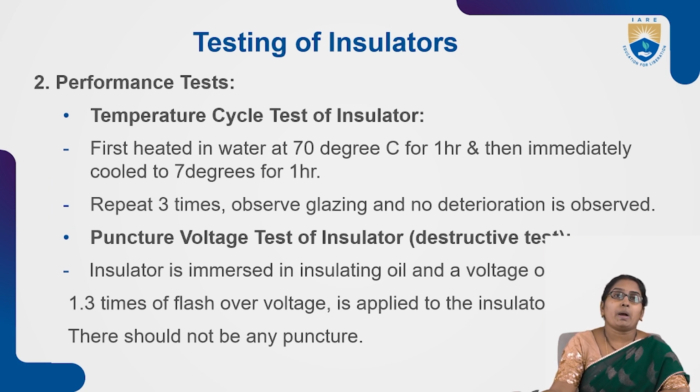Next, the second one, puncture voltage test. What is this puncture voltage test of insulator? They also call it a destructive test. The insulator is immersed in insulating oil and a voltage of 1.3 times the flashover voltage is applied, and there should not be any puncture.